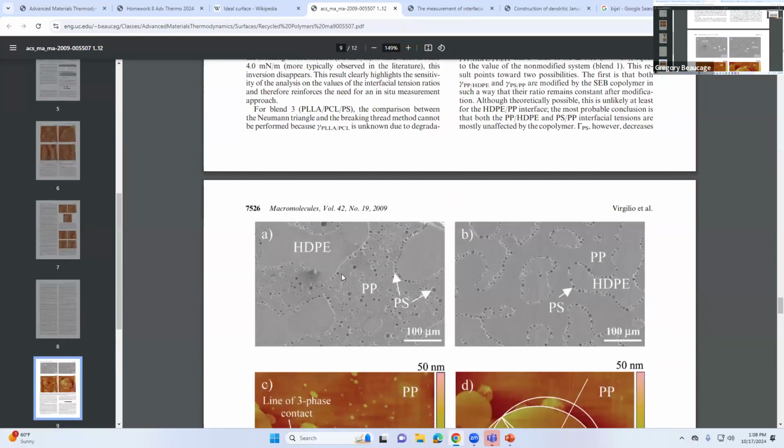It's more elaborate because he gets into this Pickering emulsion business and he explains why it happens in the paper. Like why is it transition when he adds that copolymer, it goes from that to that. So there's quite a bit of difference. In other words, here you have the polystyrene beads all over the place, and you put in 1% of that copolymer, and all of a sudden it all sticks to the surface. And using this method, he can calculate the number of these copolymers per nanometer squared on the surface of the high density polyethylene phase, which is kind of interesting.